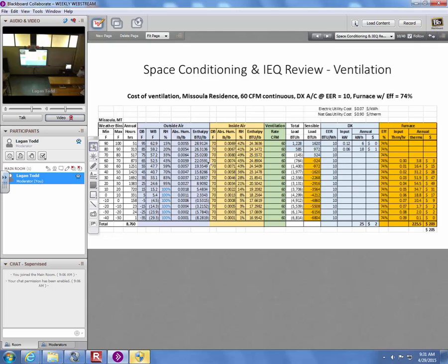Any outside air that comes into the building, whether we actively heat it with an air handler, say a furnace or hot water coil or something like that, whether we heat it at the air handler or not is irrelevant, because once it comes into the space and we have to maintain the space at 70, ultimately we have to heat that outside air up to 70. We can heat it up to 110 and drop it into the inside condition where it offsets some of the heat losses through the envelope, or we can dump it in at some cooler temp, and ultimately we have to heat up the inside air anyway.